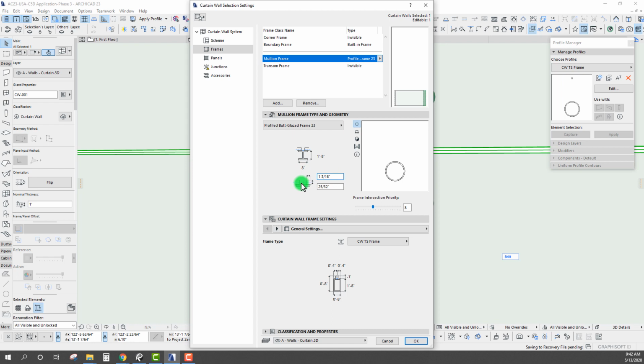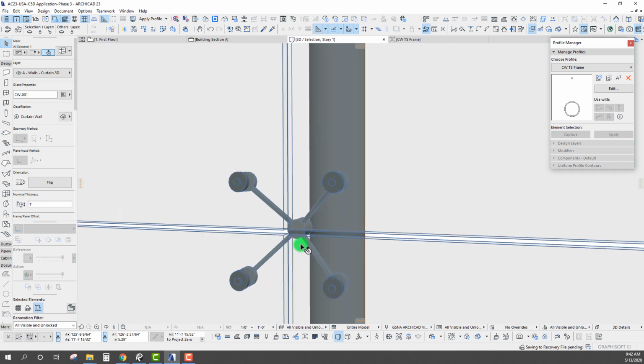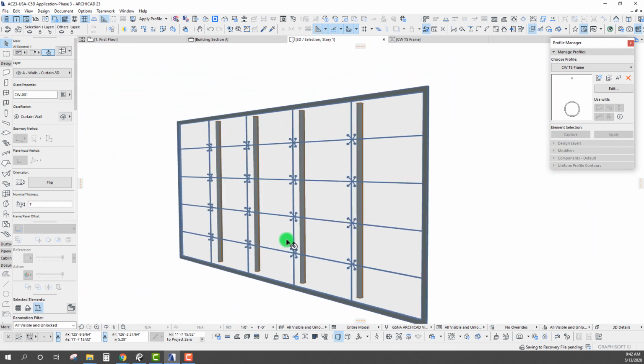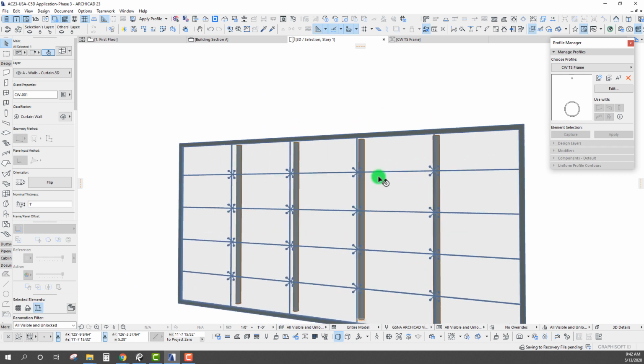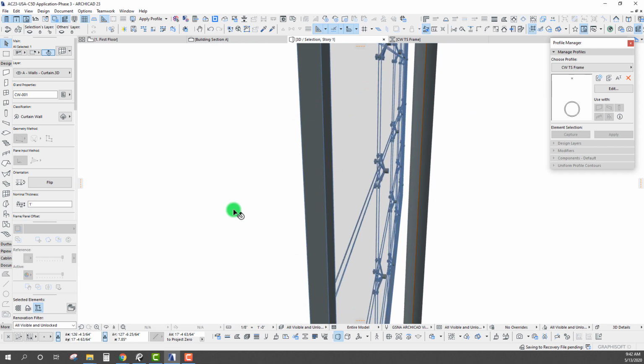So if we wanted to get that back down to our 1/2 inch total, we would need to set this as 3.75. And so that way we would have a 1/4 inch from each side of our support in the back. So let's also set this to our 1 inch thick glass as we had it in our settings there, and hit OK. And there we go. We've now started to shrink that up, which is great. And yeah, we're starting to create a bit of a support here.